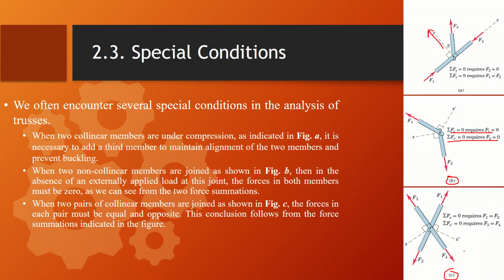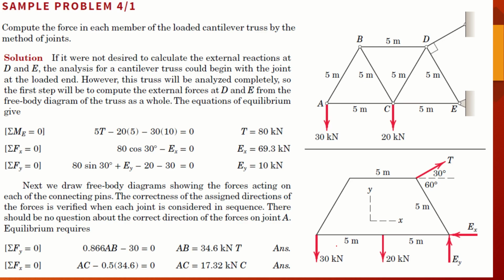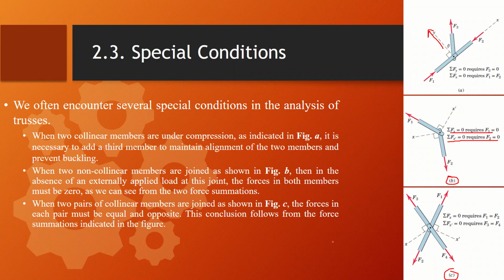The truss panels are frequently cross-braced, as I will show you right here. Such a panel is statically indeterminate if each brace can support either tension or compression.